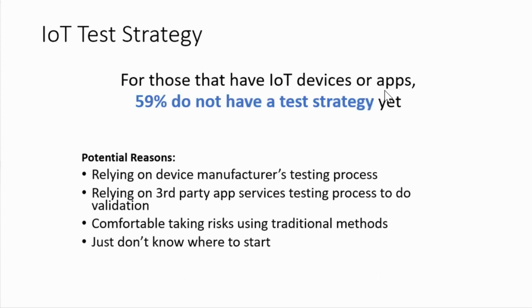Recently, I bought a sensor for voltage measurement, and it turned out there were clones of this chip out on the market that had a different address. So the I2C technology couldn't talk to the device, even though it looked identical to the real thing. That's a great example. Yeah, so clone parts. I mean, who would think that somebody would do that?